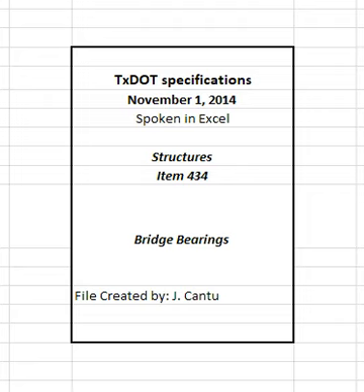2.3.3.1.2 Elastomeric rotational element for pot bearings. Provide elastomer conforming to the material requirements of the TxDOT LRFD bridge design specifications and TxDOT LRFD bridge construction specifications, and the load and rotation demand indicated in section 434.2.3.1, Structural design, with the exception that usage of virgin natural polyisoprene, natural rubber, is not allowed.